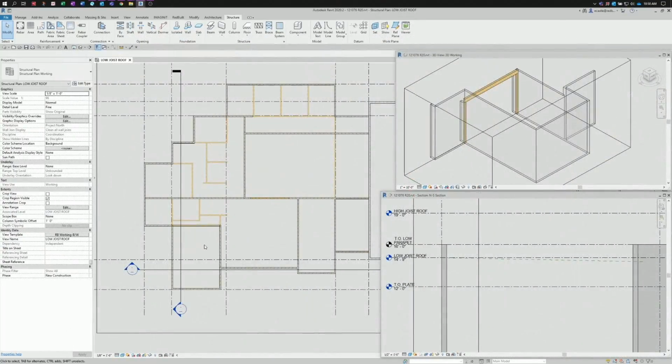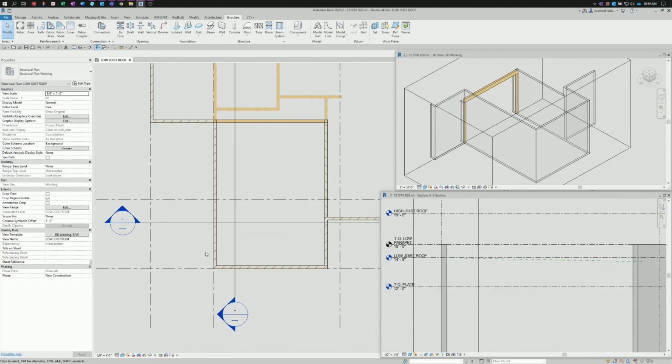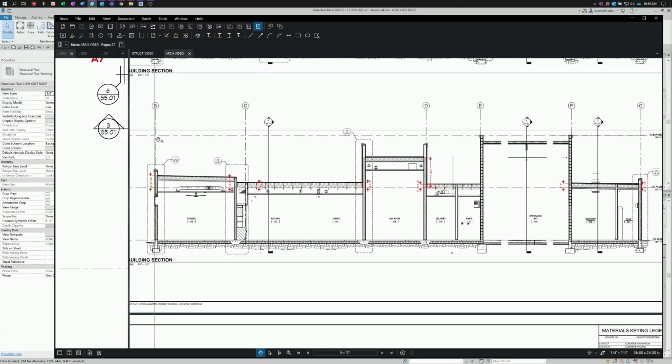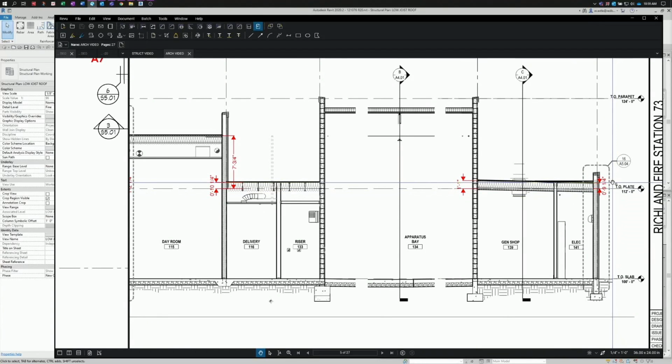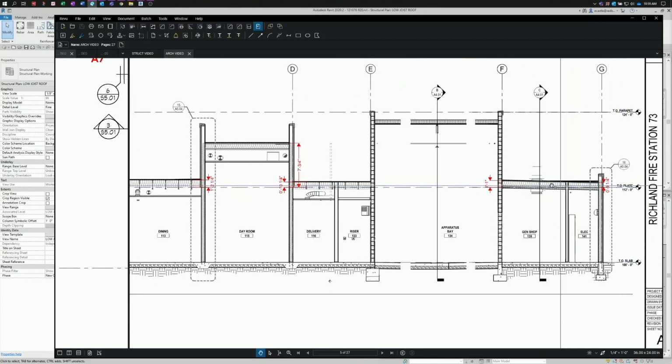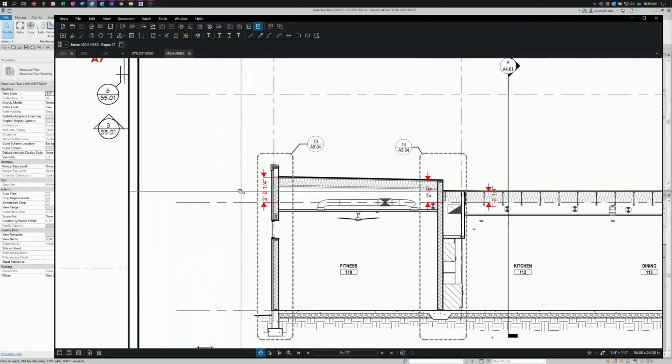The next step is to start adding ledger to our project. I've set up my views that I'm going to be working in, and to help me align the ledgers. From the construction documents, we found that the ledgers are at different elevations, and I've added dimensions from top of plate to the top of the joist and/or ledger. So now we have a base point to start from, top of plate, and then the dimensions to set the elevation of the ledgers once we've added them.